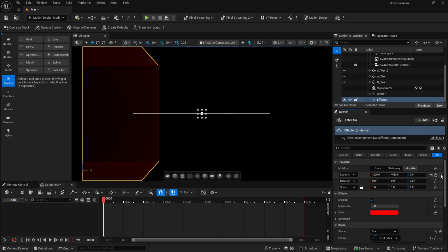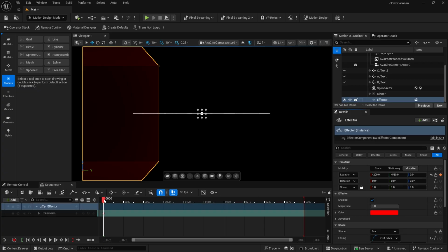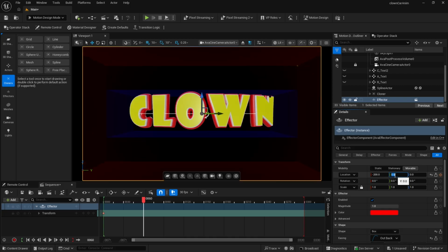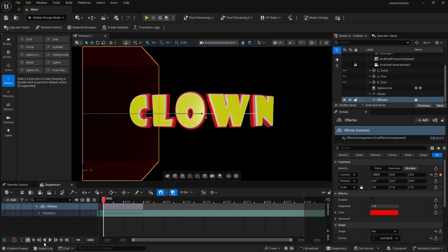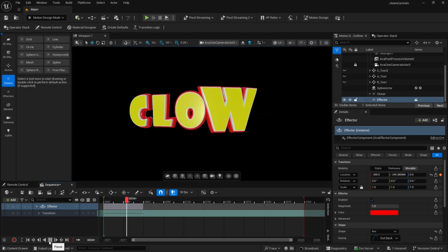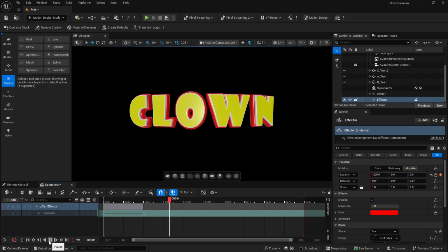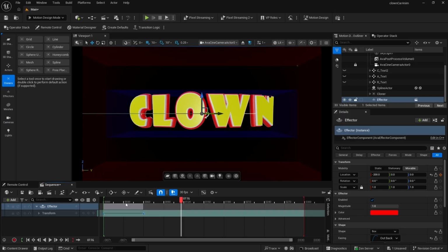I'll set a keyframe for it. And let's try 2 seconds on this. We'll see if we can change the time on this as we need, but we'll go for 2 seconds right now on this. And then I'm just going to set our Y value back to 0. Make sure we click that keyframe right there to add that in. And I'm going to go ahead and change these both to linear. And then jump back and we'll take a look. All right. So now we've animated our first text.